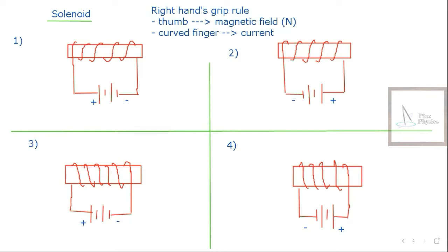You see the first one, the current flows from positive to negative. So you need to refer to the direction of current in the solenoid. After that, use your right hand. Then you see where your thumb points. This one will be north, this one will be south. Curve in front, then curve to the back. You can try using a pen to curve it.